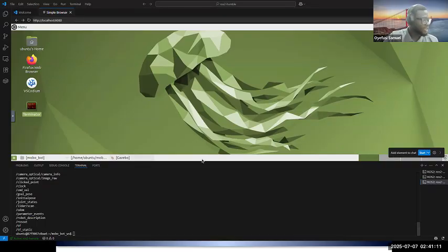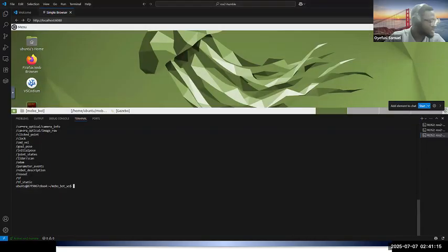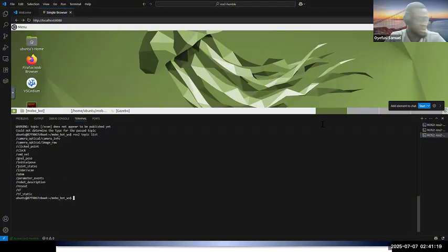So you see that over here in the terminal, when I do ros2 topic list, we have cmd_vel, we have the camera topic, we have TF, like Devin told us. TF is a very important topic. That's like the basic that we need. And ROS out, robot description topic, and odometry topic. Odometry is what we use to track the robots. Then joint state. Now we want to look at the scan topic, but I don't think the scan topic is here yet.